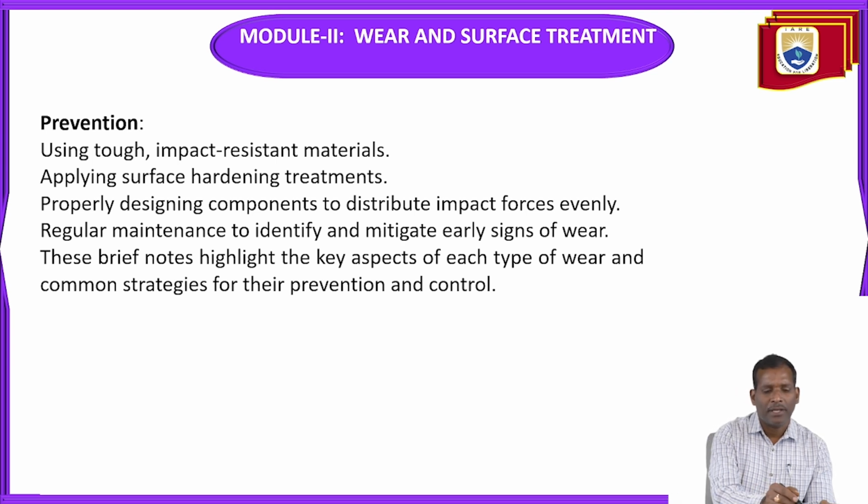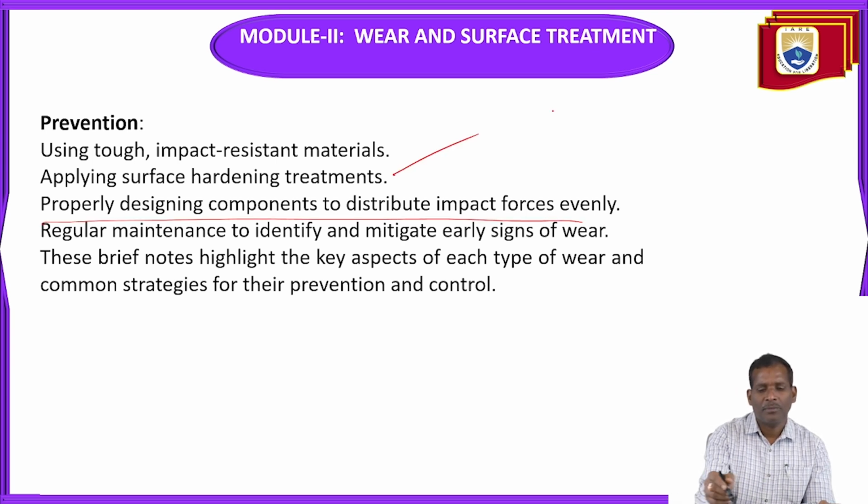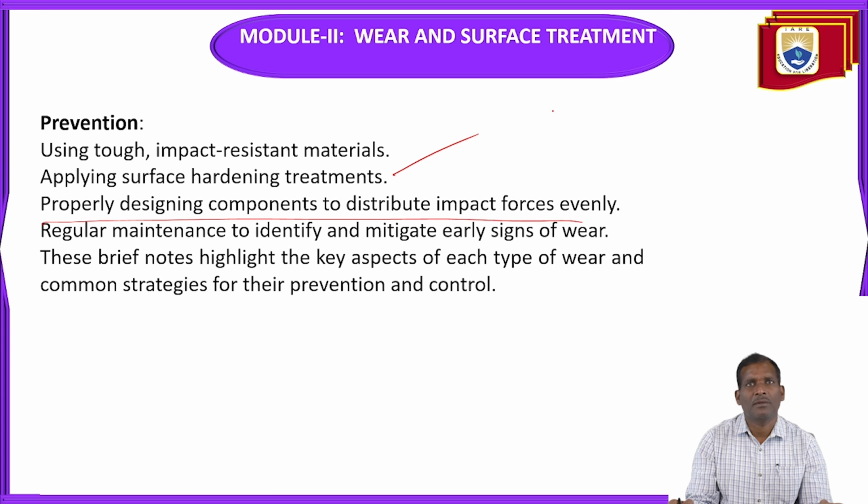Properly designing components to distribute impact forces evenly. We have already seen this in a previous question. Minimize the stress concentration. Wherever sharp corners are present, use a large radius to minimize the stress concentration.